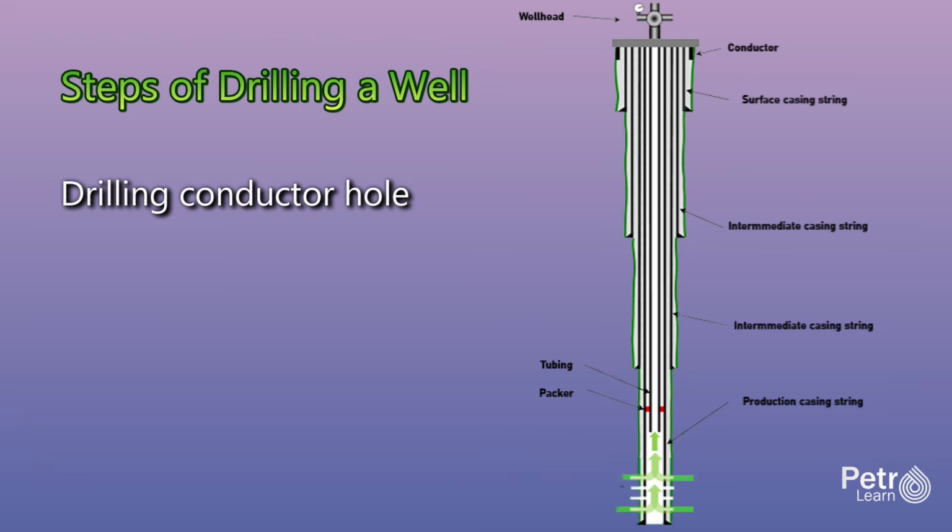Above the drill collars, regular drill pipe is added with optional heavyweight drill pipe in between as a transition zone. Drill pipe is typically 30 feet long with threaded tool joints at each end and has an outer diameter of 5 inches and wall thickness of about half an inch. The kelly, a 40-foot section of square or hexagonal pipe, is connected to the top of the drill string.